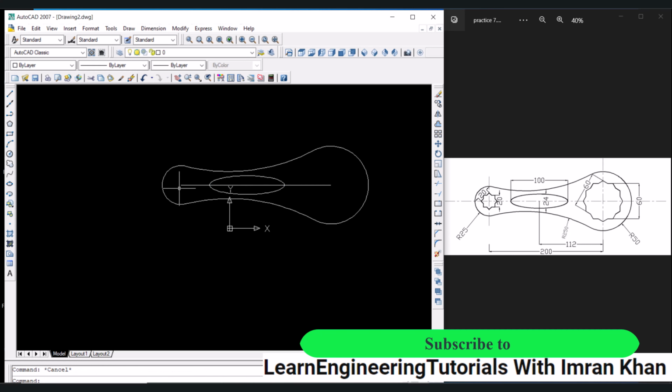Press escape. Now we have to draw a square over here and a hexagon over here. So click on polygon. For a square the number of sides should be 4, so press enter. Center, so click over here, click on circumscribed, and the radius should be half of the value given, which is 20, so the radius should be 10, enter.